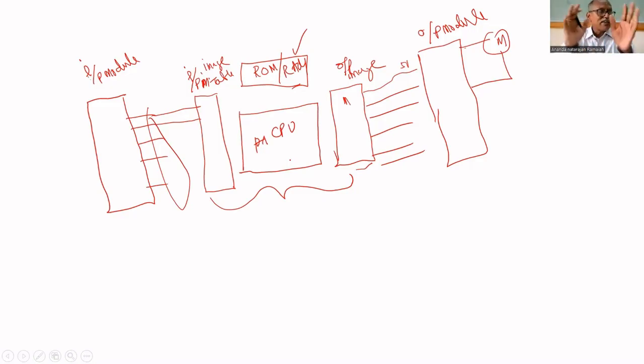But you can write it in the front end. I want to run a motor by using PLC. First, I have to connect a push button in the input module. Let us assume that it is connected to the memory location X0. Here 5 volt is available in the input module, and it is connected to X0.